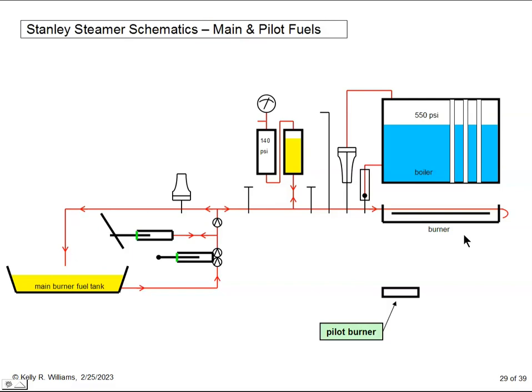So we use a little burner, just a tube about 6 inches long. It's called the pilot burner, and it burns continuously when the car is in use. Here it's shown separately, but it's actually located inside the main burner. When fuel vapor starts coming into the main burner again, the flame of this little burner lights it off.